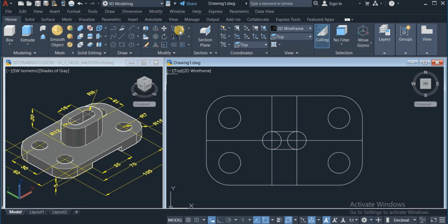Okay, so click on trim, and trim this out. Also trim this out. Okay, so next I will draw another circle of radius 12. So come over here again, click on circle and choose center radius. And with here at the center, enter 12. And repeat the same on this other end.